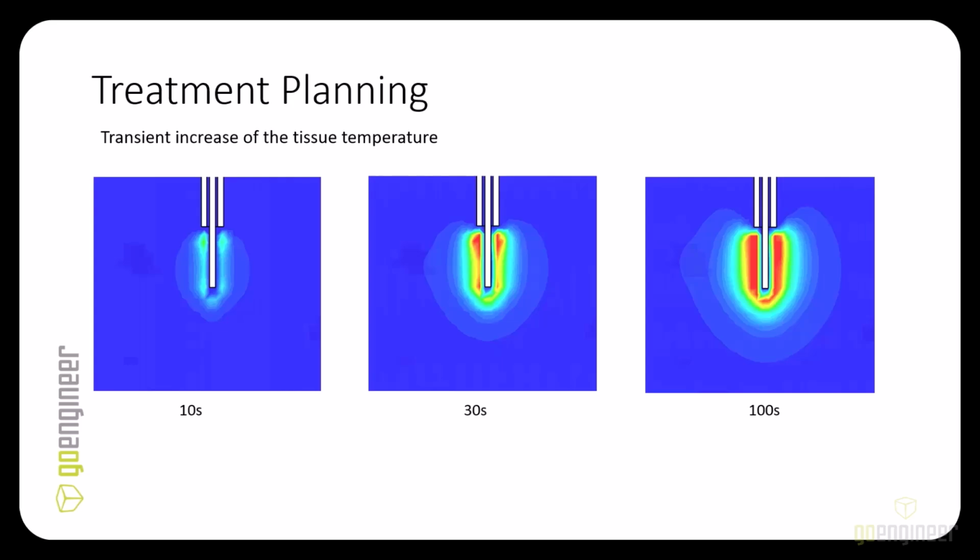The power needs to be applied for another 3 to 4 minutes until the malignant cells are destroyed due to excessive heat. This is exactly where simulation can provide insights into treatment planning. If the power is applied for a longer amount of time or a higher amount of power is deposited, it could potentially destroy surrounding cells that are healthy. Another challenge is, as liver cells get heated up, their electrical conductivity changes as the phase state of the matter transitions. So it's important to take into account that temperature-dependent conductivity to perform a full bidirectional electromagnetic and thermal analysis in order to predict the maximum rise in temperature accurately.